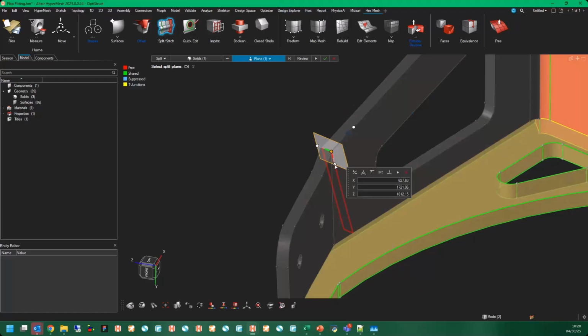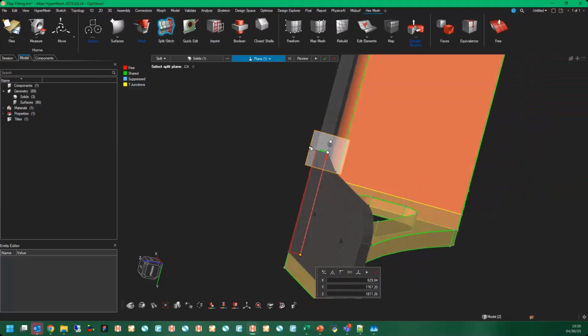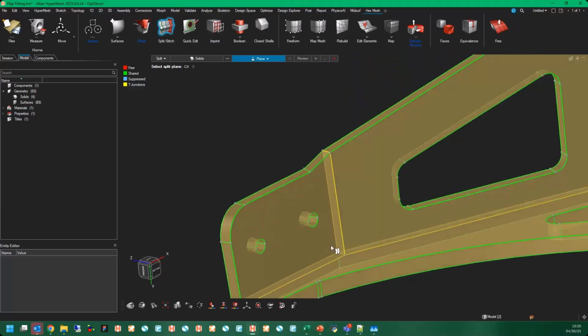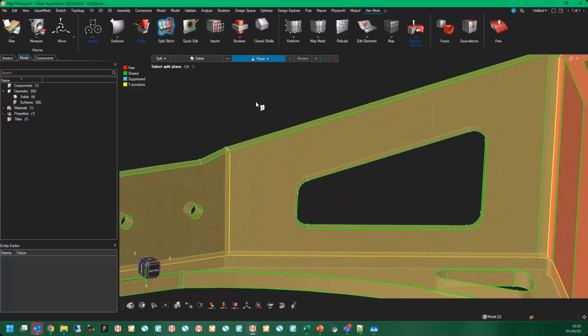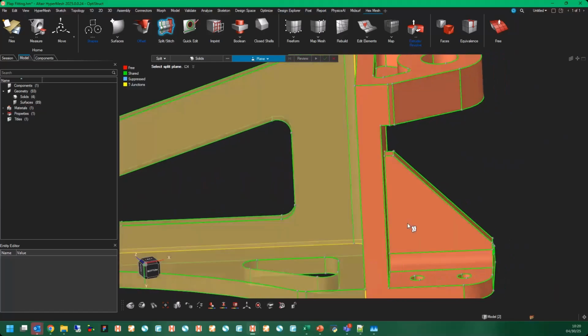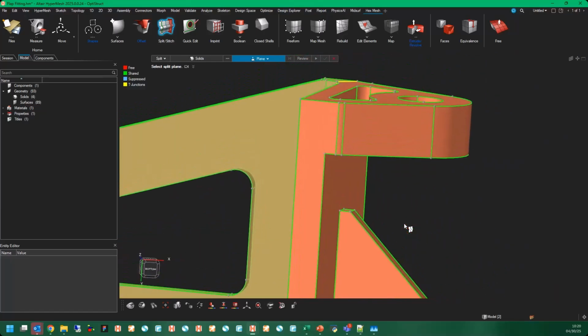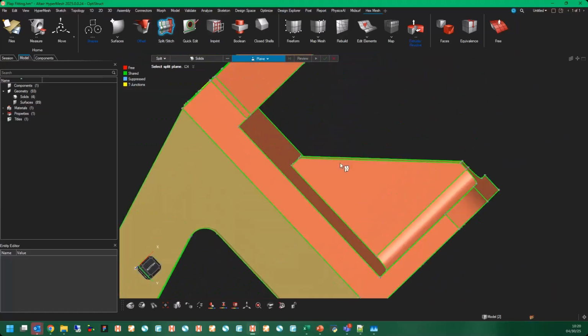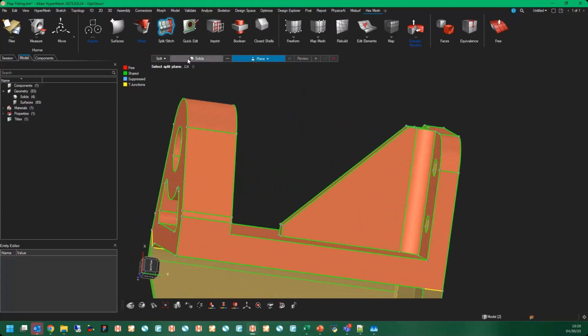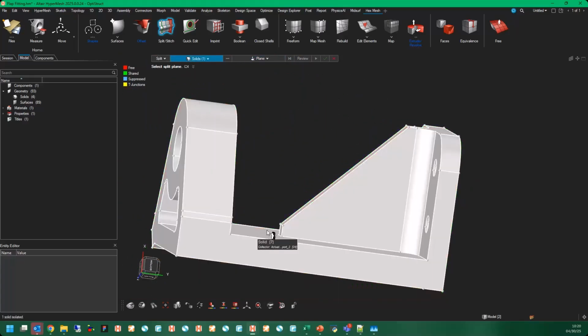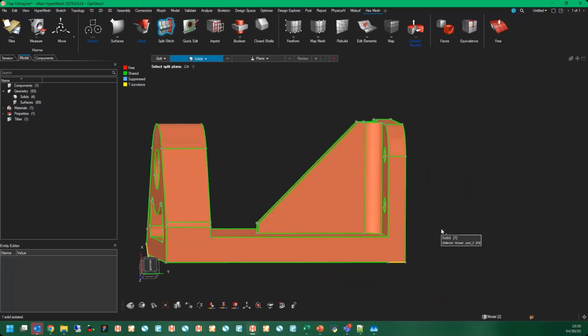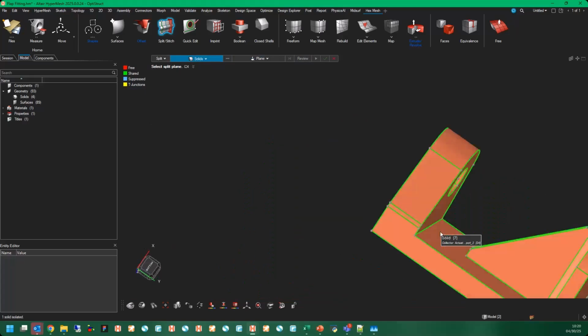In this case, I'm going to drag my points. I'll grab that edge there, and then make sure I capture the edge exactly and don't create a sliver surface. I'll make sure that point is there. And now that's split up. All right. So now let's turn our focus to this side over here. And like I said, now that we have the part kind of divided in two, we can just focus on this one. And the flow directions are a little more clear here as well.